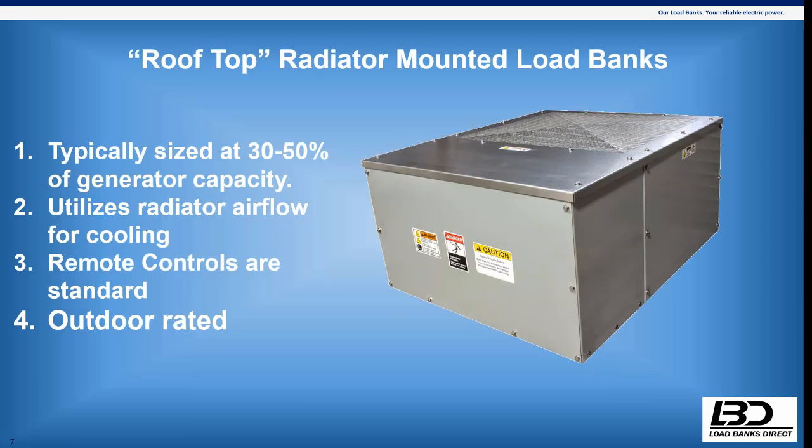The nice thing when a packager does all the installation, whether it's a rooftop onto a factory housing or a custom packager, a Pritchard Brown enclosure, a Robinson enclosure, where you've got a big genset. We could do a duct mounted load bank as big as 1,000 kW. It's UL listed, and it's a big 2,000 kW or 2250 kW generator.